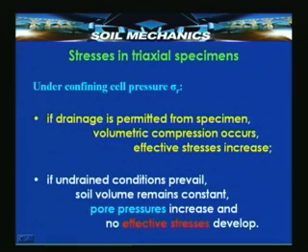Since the behavior of a soil under stress is very much controlled by the stress that it has experienced in situ, we must recreate the in situ stresses in the specimen that we use in the lab, and that is the reason why we apply a confining cell pressure sigma r whose magnitude is equal to the confining pressure that is expected to exist at that depth from which this specimen has been collected.